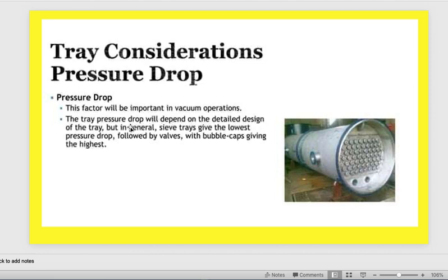And there is a famous question: what is more compatible with the vacuum processes, the tray tower or the packed tower? Don't rush. It is the packed tower. Why the packed tower? Because the tray tower holds a liquid level on each tray and increases the delta P. For the vacuum operation, you need to make it easier to make suction for the vapors going up through the column. So it's recommended to use easier, no delta P, easier pressure difference, which is the packed column. The packed column is preferred in the vacuum applications.